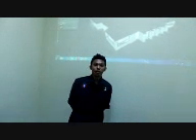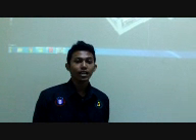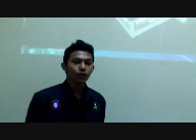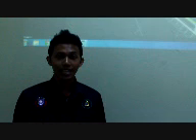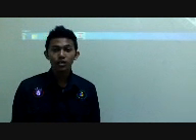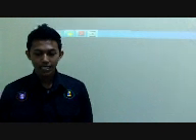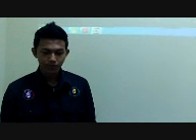That's all from me. Hello, now I want to proceed with our presentation on the lighting system design. We use Dialux Evo 3 software to design the lighting system. This is our building. We use 3 types of lamp to design this lighting system, which are double fluorescent lamp, LED, and recessed luminaire.